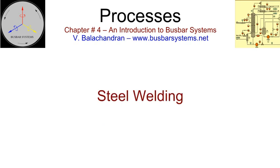Steel welding. Steel is used in the busbar systems for the manufacture of indoor and outdoor support steel structures and enclosures of non-segregated and segregated phase bus. Depending upon the thickness of metal, two types of welding processes are generally adopted: manual metal arc, MMA, and metal active gas, MAG, also known as CO2 welding. Steel sections used to support steel structures are heavy, with a thickness of 6 mm, quarter inch, or more. Steel sections used for the manufacture of enclosures of bus duct are much thinner, with section thicknesses varying from 3 mm, 1/8 inch, to less.